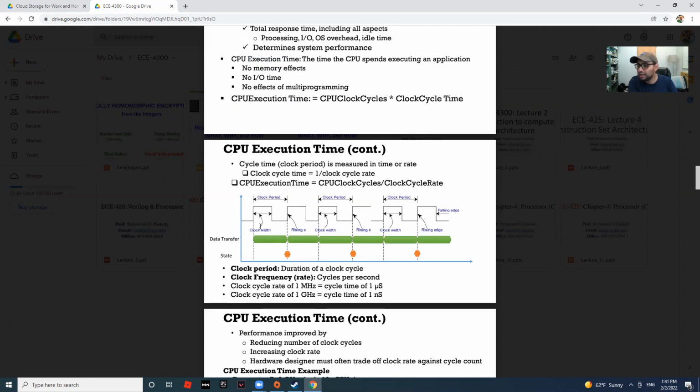If you are electrical and you just think about electrical, those are RC circuits, crystal. So that means, if I charge from the low to the high, the time I take for charging is the positive edge. The time from the high, losing the charge to the low, that's the negative edge. Make sense? If you studied 3300, you will find out that in an always block in Verilog, you have to go on one of the edges, and in 90% of our practice on campus, I believe it was the positive edge, right? Posedge of the clock.